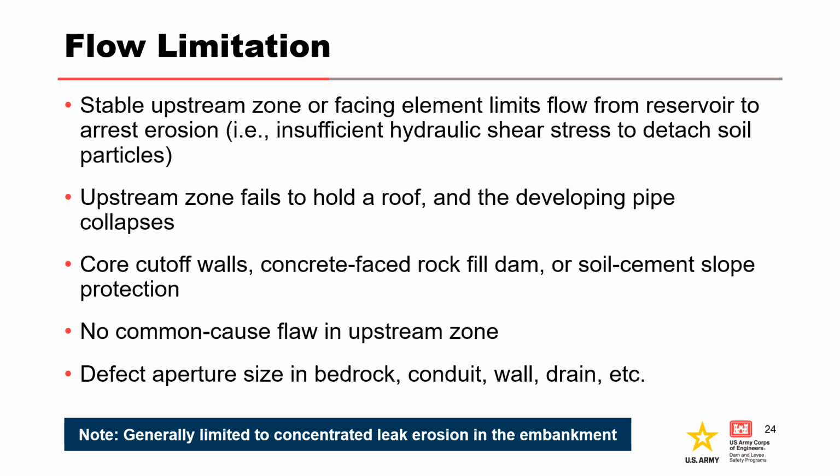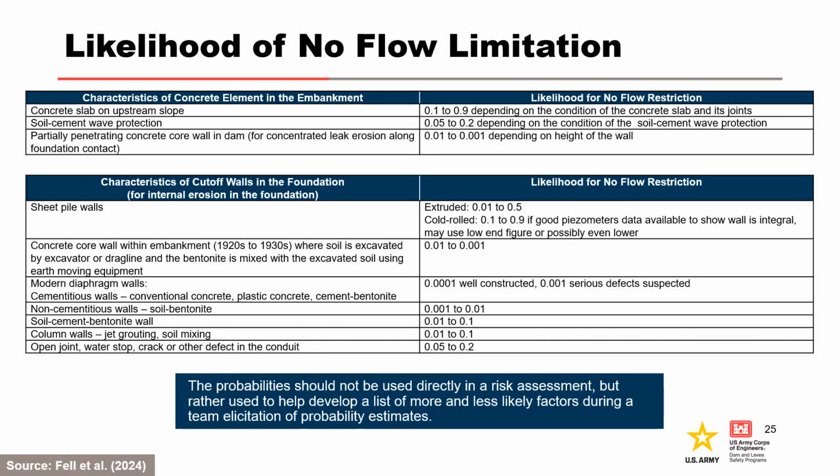Upstream fine-grained blankets beneath and around the dam may not prevent initiation of erosion, but may be effective in limiting progression. Flow limitation may occur due to an increase in head loss across an upstream blanket. This slide provides some guidance for concrete elements in the embankment and cutoff walls in the foundation.